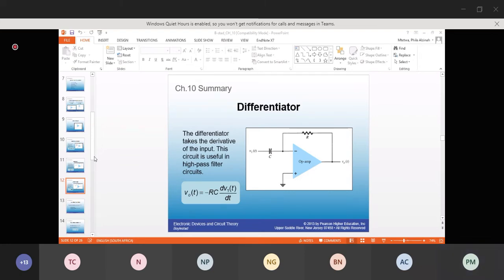So when you're explaining how a transformer works, don't say the transformer can step up or down a voltage. This is a particular project, doing a specific job. It's a particular transformer, so it's not about transformers in general. Be specific. This transformer will step down the voltage, and then this voltage will go through the diodes, which form a full wave bridge rectifier, where it's converted from AC to DC.